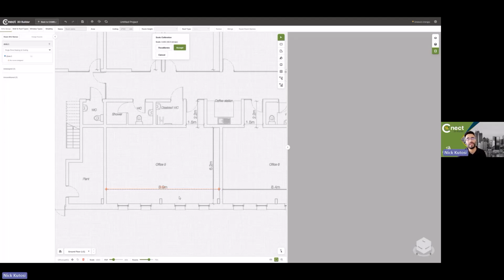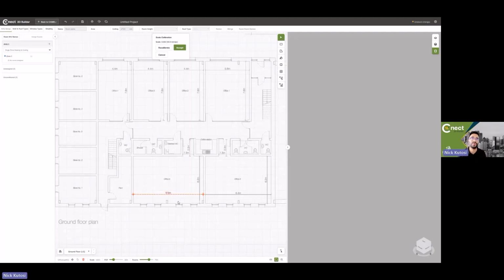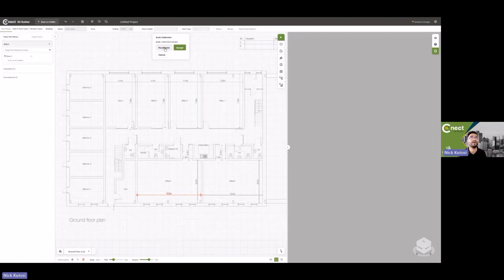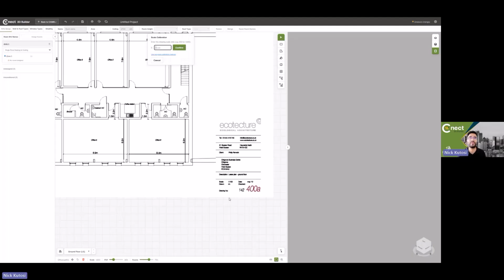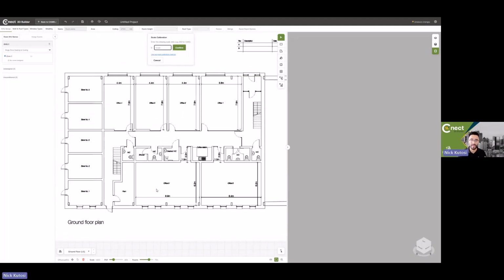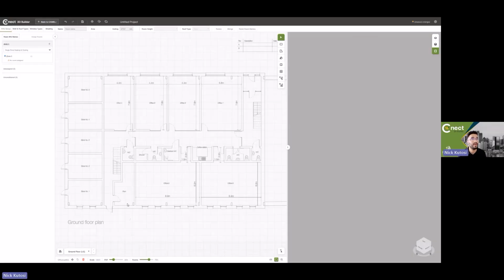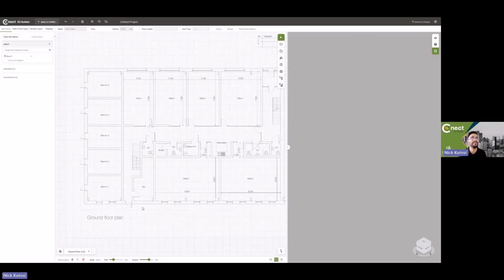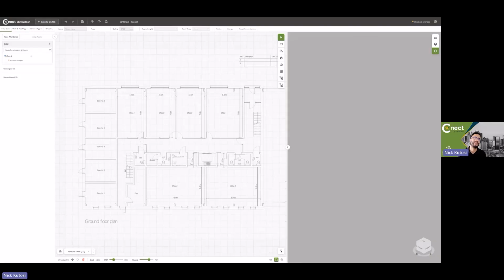So that can be useful even just as a sense check to make sure that you've got the right scale, because even if there's a scale written on the PDF, the actual PDF might have been saved in a different size. So it's one thing to just double check that you've got the right scale set up there. I'll just go ahead and type in 1 to 100 manually, as I know that's correct for this PDF. And then you'll see that goes as a background.